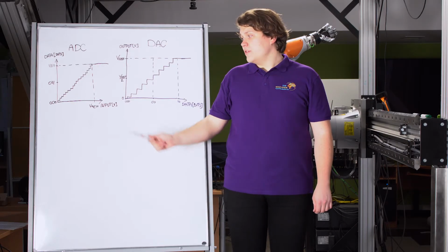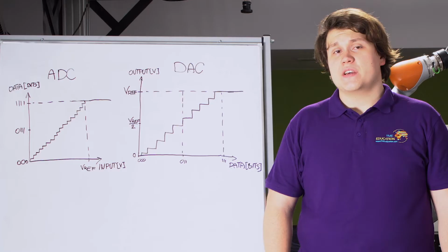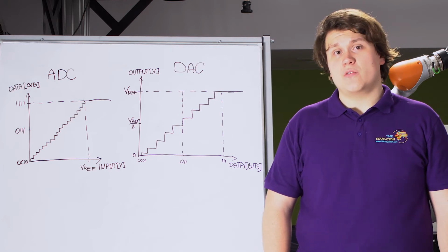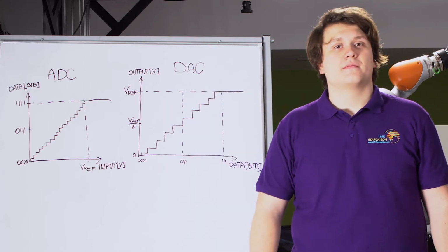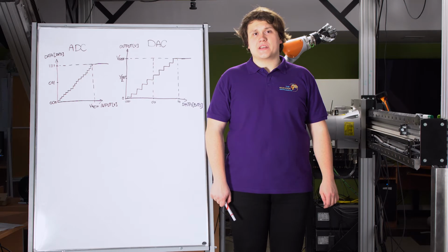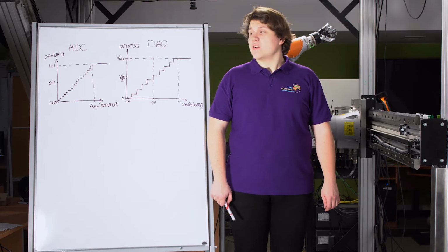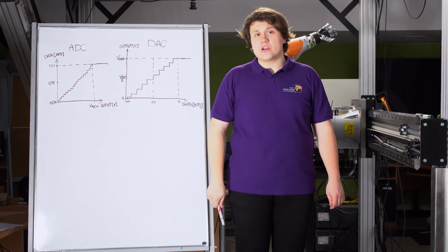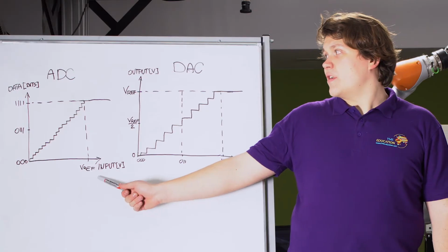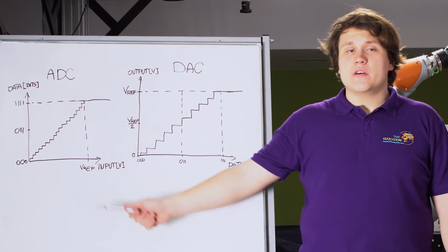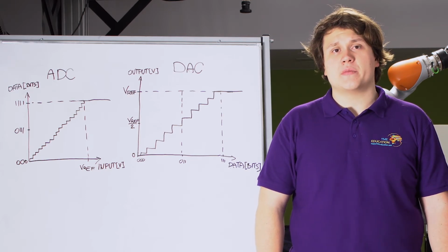Exceeding the value of the voltage reference may cause damage to the system, but sometimes we have to measure voltages that exceed our range, or they are so low that we cannot optimally use the range of our converter. Then, it is important to condition the signal. There are many different treatments that allow our signal to match the expectations of the converter. For example, when we have a 7 volts signal and the maximum value of our input in the converter is 5 volts, we can use a voltage divider made of 2 resistors, for example 30 and 75 kilo ohms.